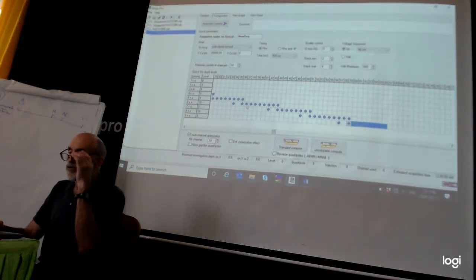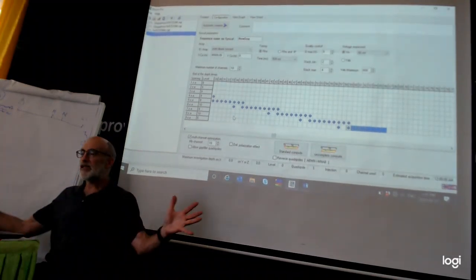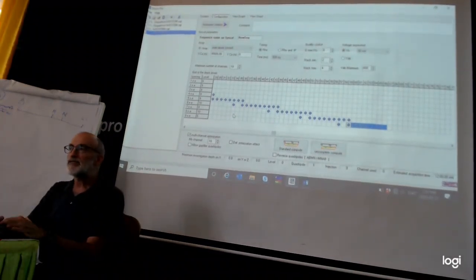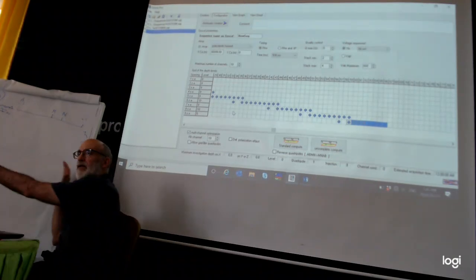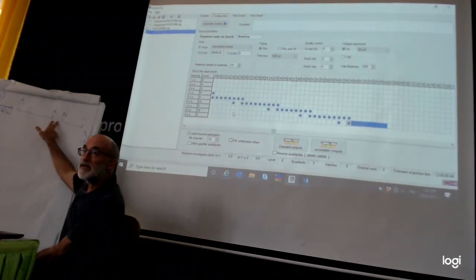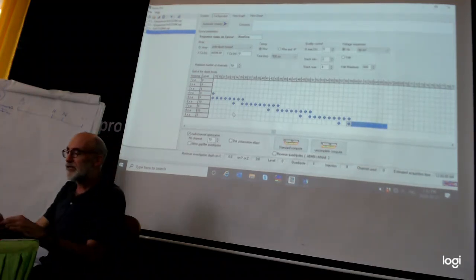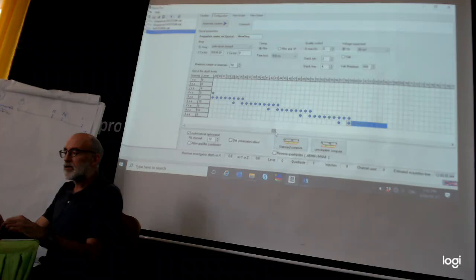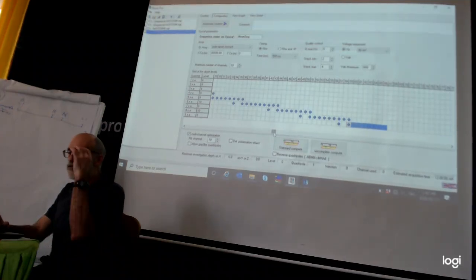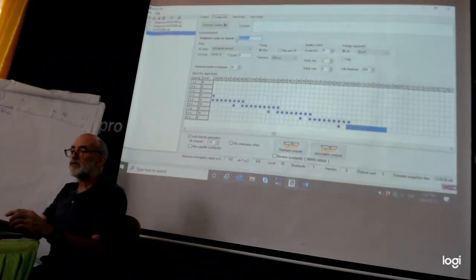I chose 8 because with the pole dipole, you can get down to the 9A level, and that gives you a wider MN to get a better potential voltage and still keeps the resolution.